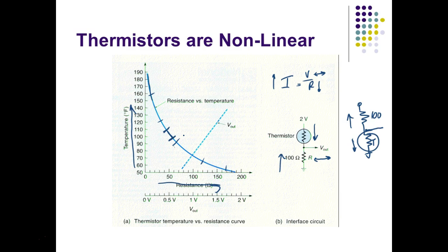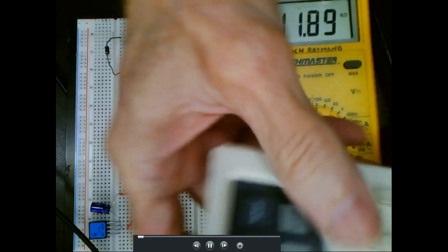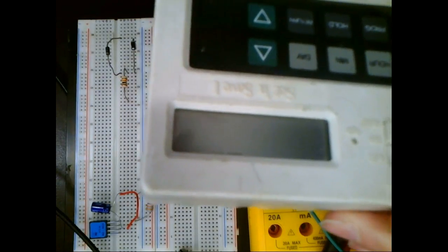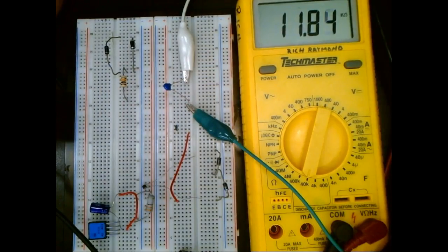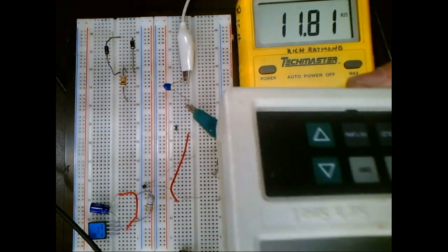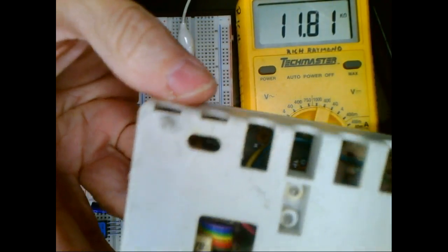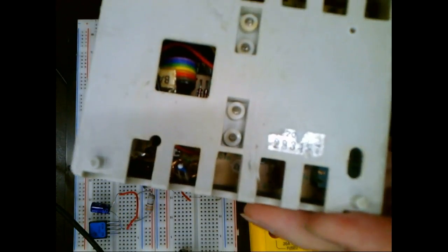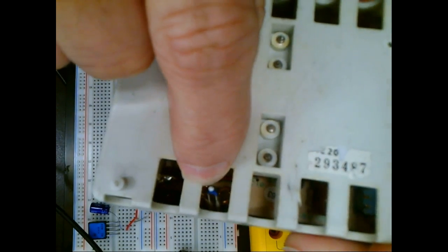This is one I got out of my house before I upgraded. So this is a digital thermostat that replaces the old bimetallic strip that used to come out. Most houses, if you buy a new house, they're definitely going to come with a digital thermostat in there. But notice it's got all these vanes in the back, and I flip it over, and what's this right here? A little white, that's the thermistor.